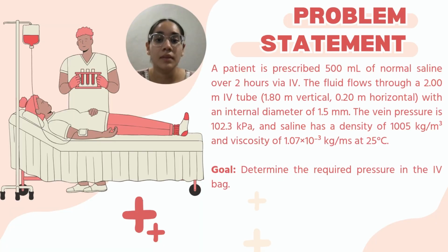The following problem is used to determine the required pressure in an IV bag to deliver 500 milliliters of saline solution over 2 hours, considering the tube dimensions, vein pressure, and fluid properties given.